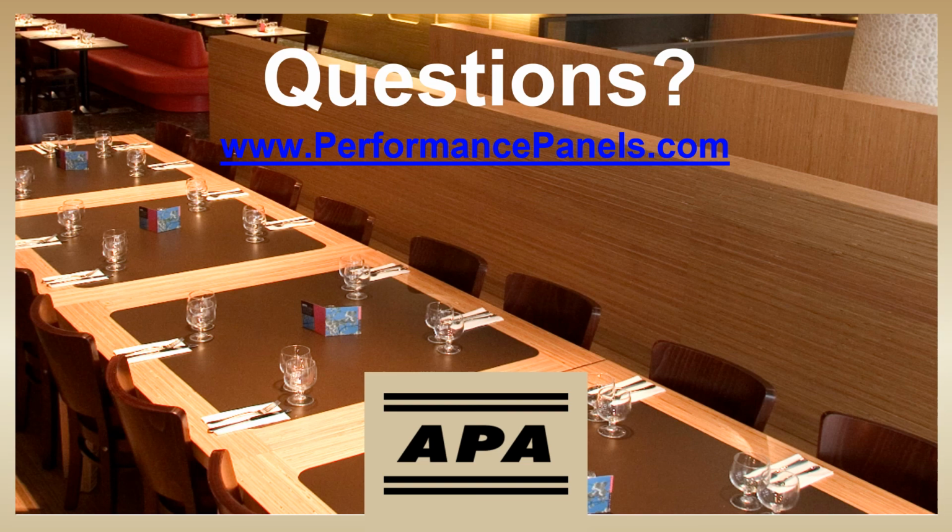So if you think about it, if OSB was used as a concrete form, it would likely be for one pour only. And that's generally not what people are looking for with concrete forms. They usually want them to be reused. So an Exterior bond classification is probably going to be desired. And this is going to lead you to plywood panels with a minimum C grade veneer, as well as panels overlaid with MDO or HDO.